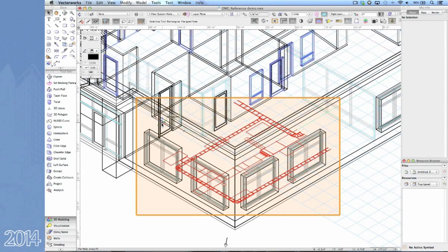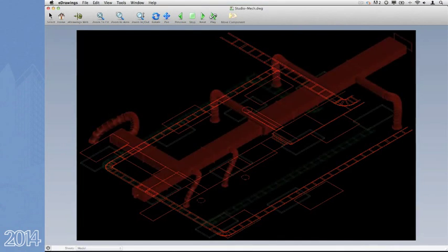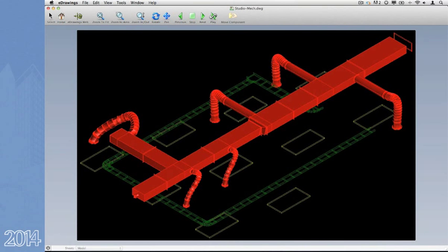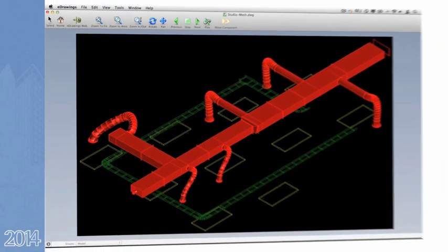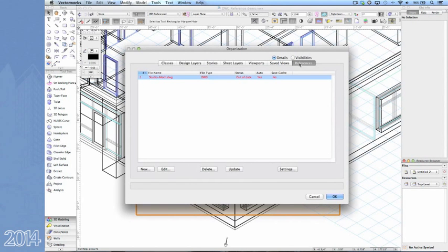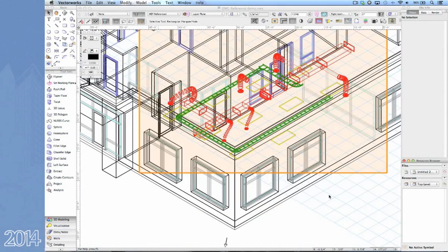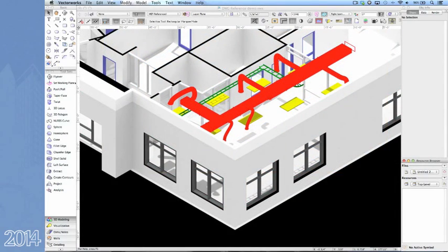Like always, updates and changes are bound to happen. In this case, our external proposal evolved into a 3D model. We'll run the same process. Once the changes are agreed upon, I'll replace the original reference file with the new one. Now, back in our main Vectorworks project, if you open the Organization palette and under the References tab, you'll see our references are out of date. By hitting the Update button, our latest 3D proposal is now up to date. This direct workflow is a huge step forward for those who need to ensure team collaboration.